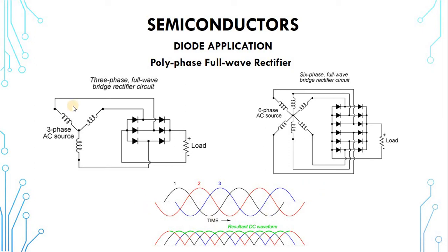So you can see that already, without even the diodes, without even the capacitor, with the 3-phase, the current never gets to 0. The load does not see the current dropping to 0 in the first place. So you can imagine what happens when you now apply a capacitor to it.